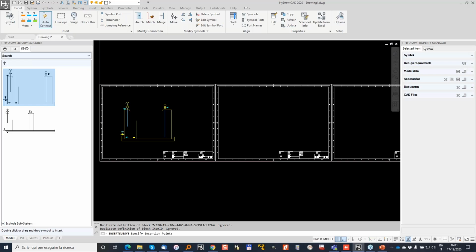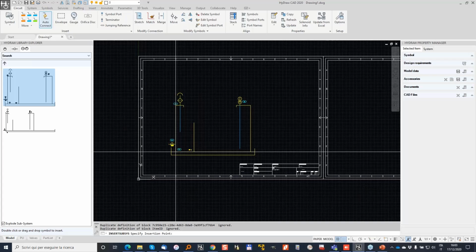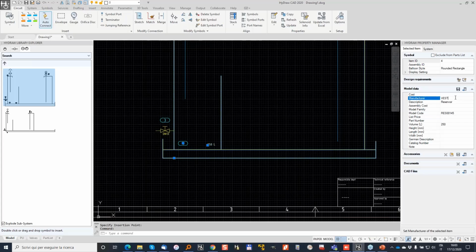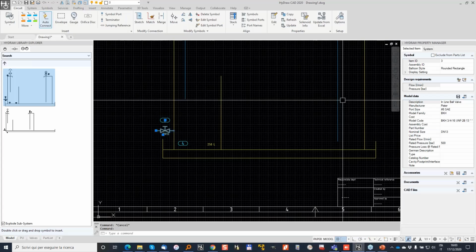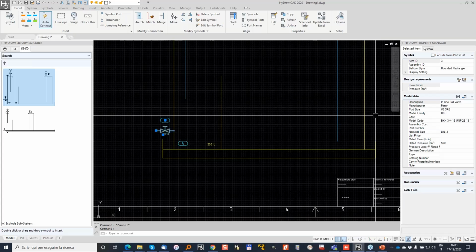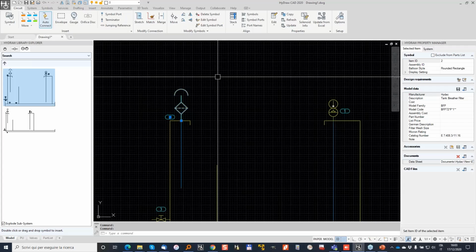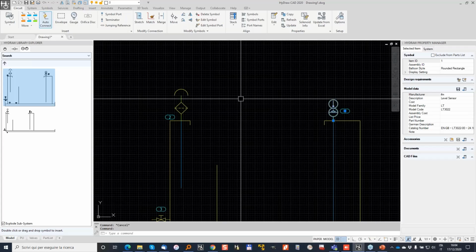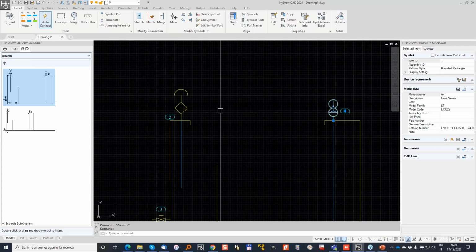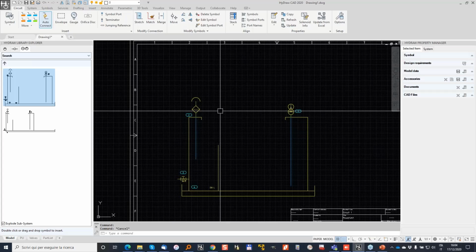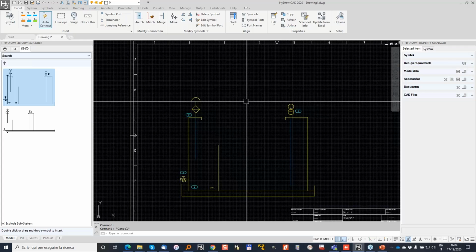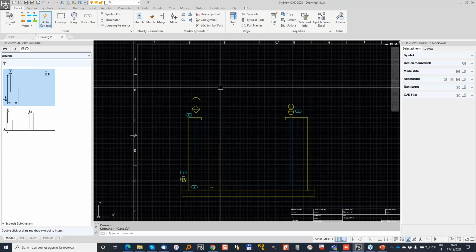I put a reservoir. In this case, that's my standard module. It's a reservoir with some model code information, manufacturer and volume. Also the shutoff valve is a piston shutoff valve. We have a breather filter, and we also have a sight level gauge. The advantage of subsystems is that you can frame a part of a diagram, also with model data information, and store it in the library for future use. So it will make it easier to build new diagrams.